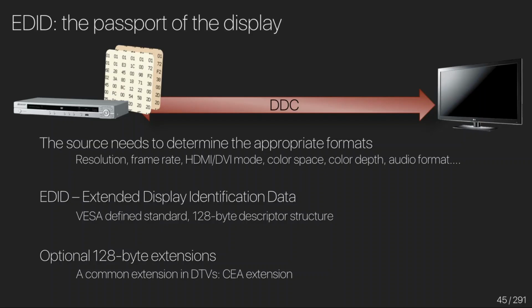And nowadays we also are entering the world of DisplayID, which will be another extension that is used to accommodate for even more stuff that no one envisioned back when HDMI first came out. The experiments we've been doing with it have been incorporating these ultra wide resolutions where the standard EDID doesn't give enough memory to even represent the larger number of pixels that you are using. With a standard EDID, once you get over 4096, it tends to break down. So to go beyond that, you need to go to DisplayID.